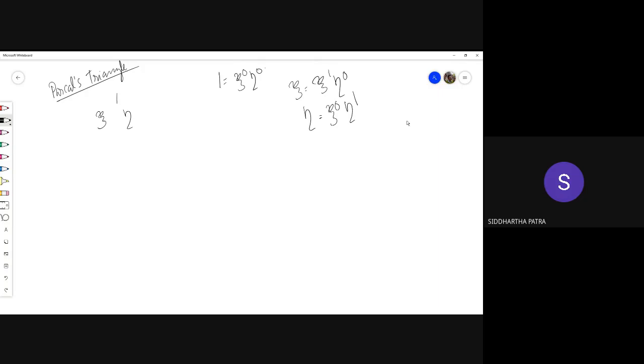These are the terms that participate in making the shape functions. The first three terms make the shape functions of the CST element. If you recall, for a CST element, the shape functions are xi, eta, and 1 minus xi minus eta.